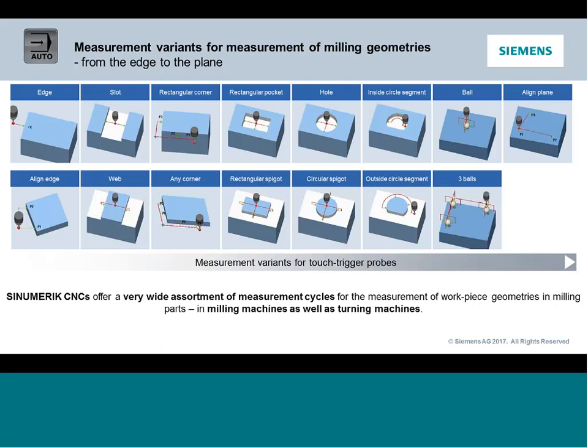In jog, you're just going to run that one cycle, where here I may actually combine a couple cycles. So maybe I need to do an alignment off a couple bores. Well, instead of having one cycle that allows you to do it full cycle, you can use the two whole cycles in conjunction with each other, and then do some math, write some variables, record some data. So that's where this stuff gets very, very flexible and very powerful for you.